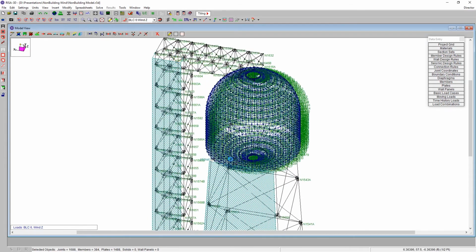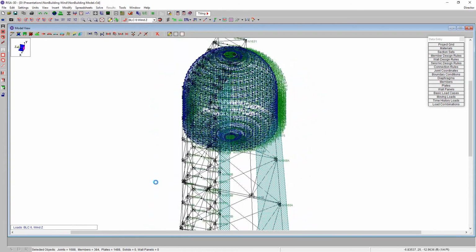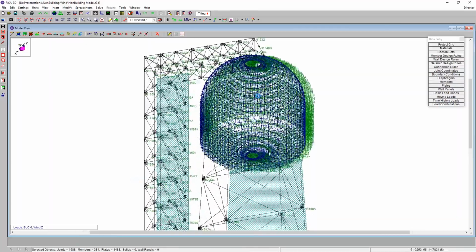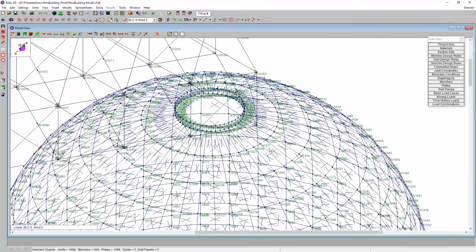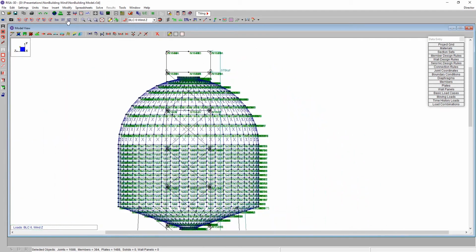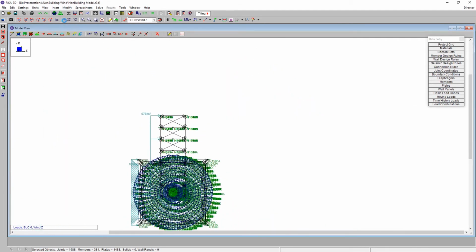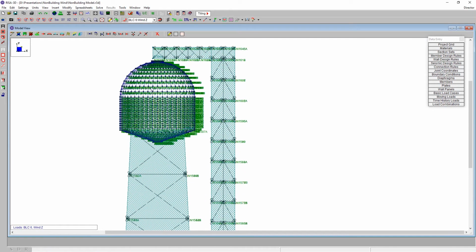and here we see the open structure load applied to the main portion of the tower there. And then all I have to do at this point is apply this as well to the part of the tower that sticks out. So we'll grab this node, that one, and that one. All right, excellent. So now, coming into an elevation view, we can see there's our wind load applied to all of those. Excellent. So the next thing that I'm going to do is apply the wind load onto the tank.